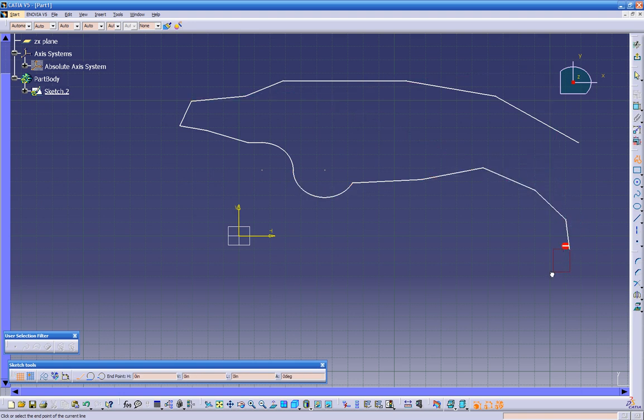Then if you hold it and drag it, it creates an arc in the direction you like to go. So as you see, now I'm going to snap again, quick tap, you can create lines. And if you want to create an arc, you just click and hold and then drag the direction you want to go, and there you have it.